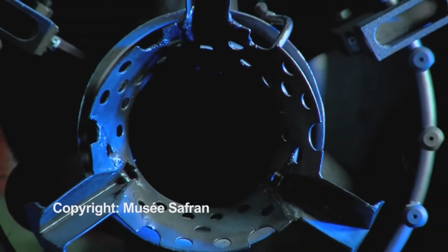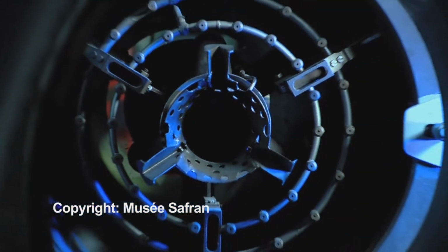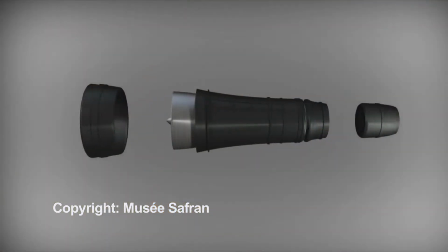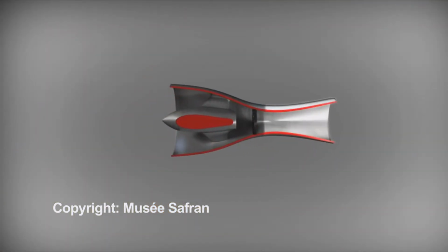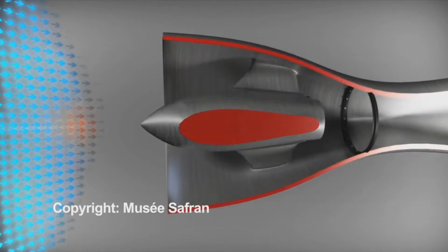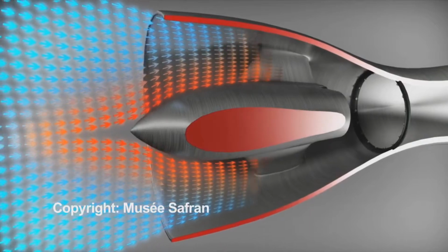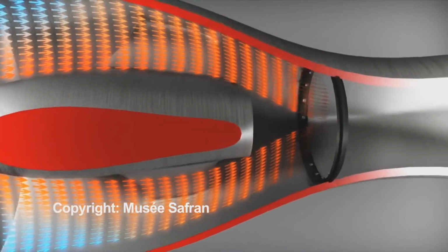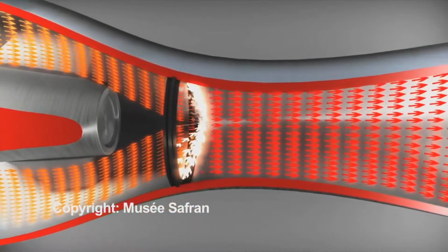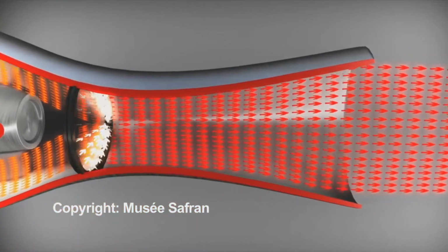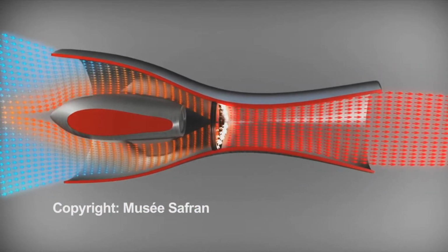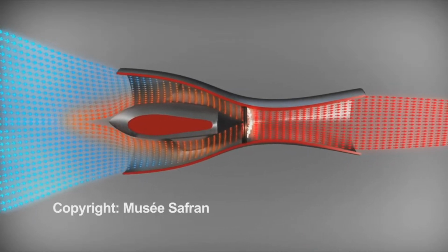When the fuel is sprayed into the engine and ignited, the air expands and the barrier forces it to leave the engine at a high speed through the nozzle in the rear. The acceleration of the air produces forward thrust. One limitation of the ramjet engine is that the air must be slowed to a subsonic velocity in order to sustain combustion of a fuel-air mixture. The scramjet engine has overcome this limitation by its design, which allows the fuel to be ignited and burned in the supersonic air traveling through the engine.